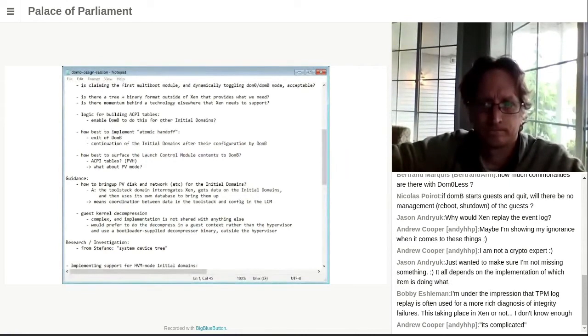So the fact that device tree is typically used to describe the hardware doesn't mean you cannot use it to describe something slightly different. For instance, the device tree that we use for device assignment to the domUs is its own little tiny device tree with just information on one node and a couple of special attributes. And that doesn't really look like any real device tree.